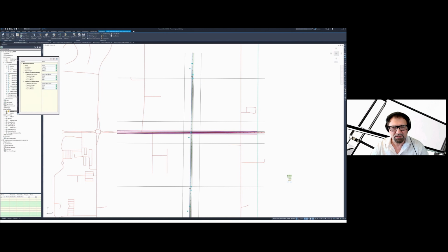Now we're gonna change the lengths of each one of the widening. So the total region length is 3,000 feet, but for the transition parameters at entry, I'm going to have a transition length of 1,500 feet. And we're going to do a simple taper or linear transition. And I'm going to do the same for the transition out, and that's going to be also 1,500 feet.